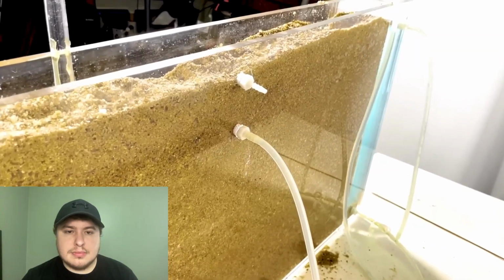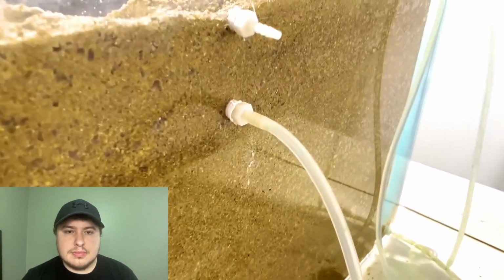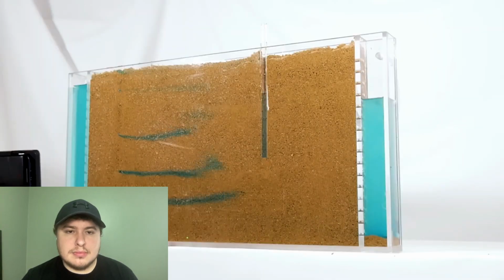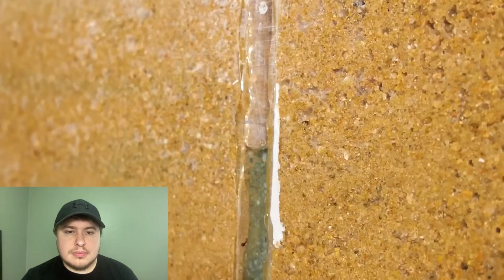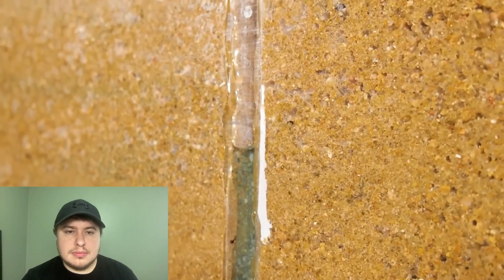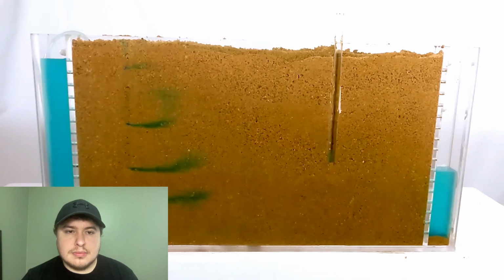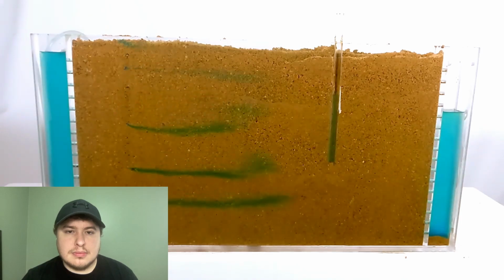Upstream of my uplift monitor, I've added a hole through the back of the model with a tube to drain seepage out. Instead of flowing all the way downstream, now some of the seepage flows up to and through the drain. And you can see this in the streamlines of dye flowing in the subsurface. Again, the effect is subtle, but the uplift pressure monitor is showing a slight decrease in pressure compared to the original configuration. There's less pressure on the base of the dam than there would be without the drain.